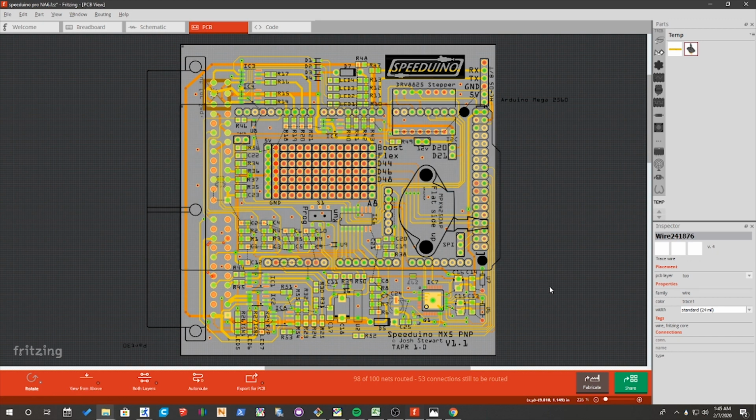I'll actually be showing you what I had to do to figure out why exactly the 12 volts that was coming into my ECU was no longer being turned into 5 volts. The reason I was able to tell that my ECU was not turning its 12 volts into 5 volts was because my ECU actually has a Bluetooth sensor on it that I wired up, and that Bluetooth sensor wasn't turning on when I turned the key on. When I turn the key on, the ECU should be receiving power, but for some reason that power wasn't turning the Arduino on, which then wasn't turning on my Bluetooth module. So I had to figure out why my ECU maybe wasn't receiving power or wasn't turning that power into the power that it needed.